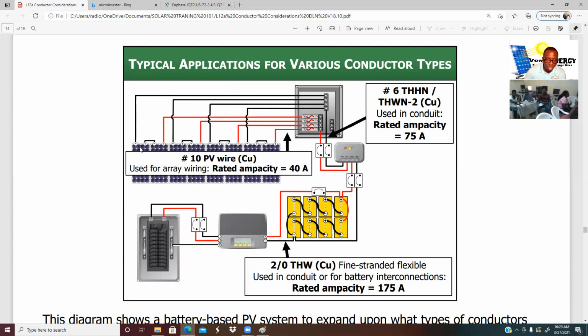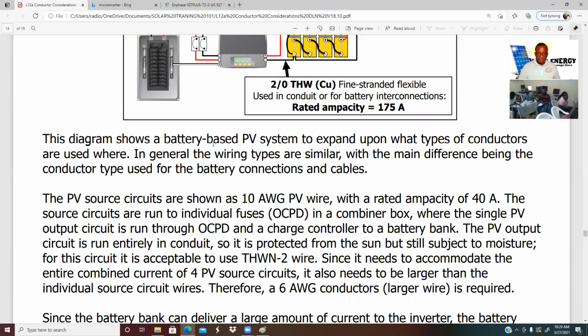So you notice that number one here, they are connected in series. The negative runs go up there. The positive run from number 2 goes into this junction box, but into a fuse. Number 2 here, the positive goes into the fuse. Negative goes up here. So you do the connection in series. These are series connections, not parallel. That's what they're saying.